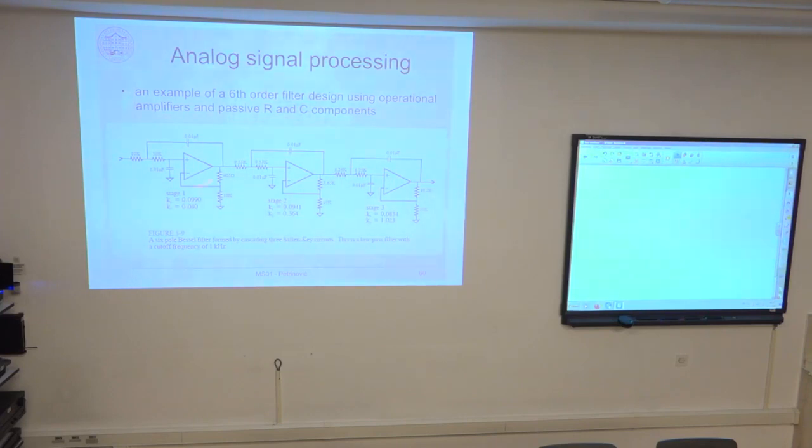And the same problem was with operational amplifiers, because their characteristics were not ideal as well. They had some cutoff frequency as well, so they were not behaving as ideal infinite amplification for all the frequency range, but simply they had first order pole going down from some maybe 10 hertz or whatever, and for this reason they had a lower gain with a higher frequency.